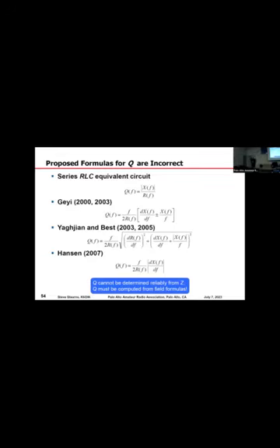It doesn't. That's the whole point. The radiation is whatever the antenna had before. These are just tricks that show you that the Q formulas cannot be right. No Q formula based on feed point impedance can be right. The only way to calculate the Q of the antenna is by integrating the fields and getting the actual energy stored. Right, that's feed point Q. Okay, next slide.